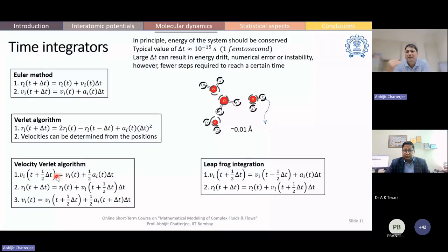You would find that the simulated values are fairly close to the experimental one. It may not match exactly, because even in experimental approaches, if you have a complex fluid, more complex than water, every type of rheometer, every technique used might give you a different viscosity at the end. But if we're talking about orders of magnitude, then the simulation technique should give you a reasonable order of magnitude value of the viscosity.